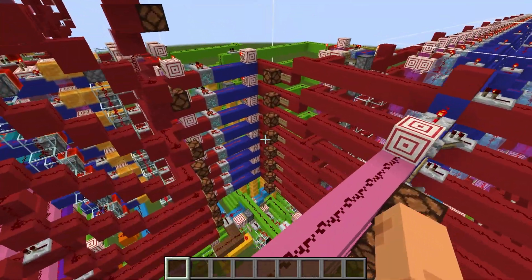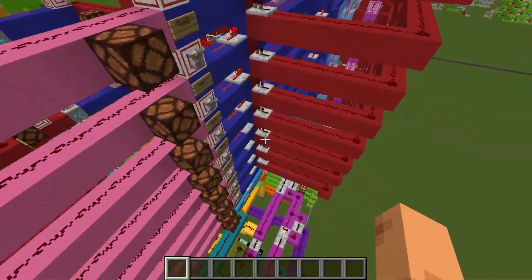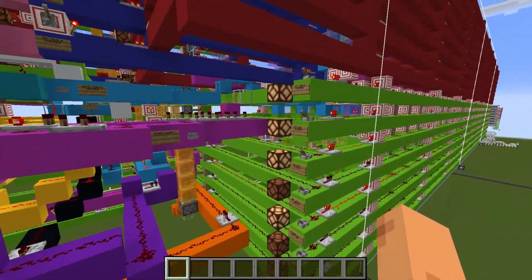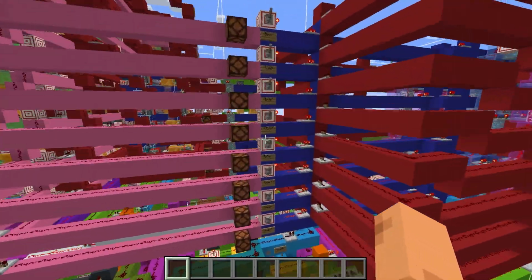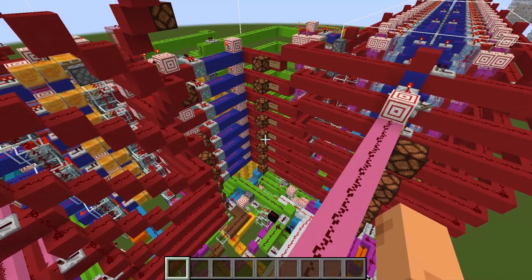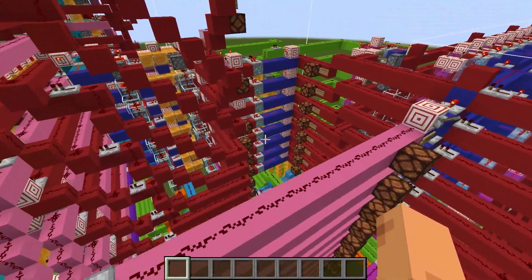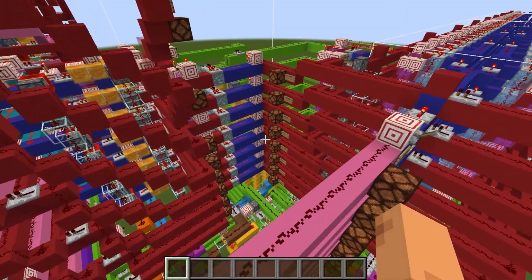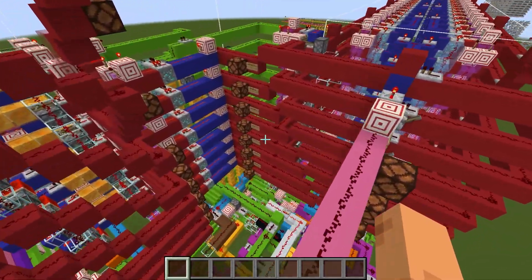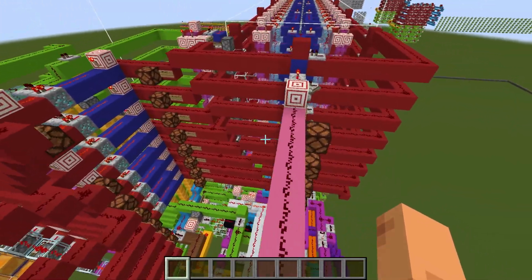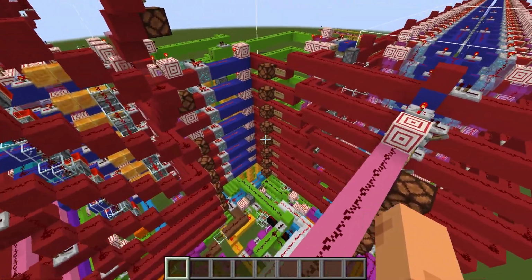I believe that is the finishing address. If we look at our program, yeah, that is the finishing address. So at the end of the program, remember we inputted our value in memory address 33, decimal 33. Our output address is 32. And those were arbitrary, but those are just the addresses we picked when we generated our machine code.